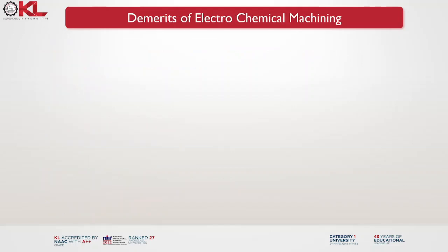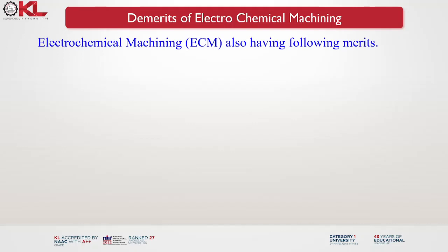What are the demerits of electrochemical machining? The electrochemical machining also has demerits. So, limited material compatibility. ECM is primarily suitable for electrically conductive materials. It cannot be used for non-conductive materials such as ceramics, plastics, and composites. This limitation restricts its application range as certain industries and components may require machining of non-conductive materials.